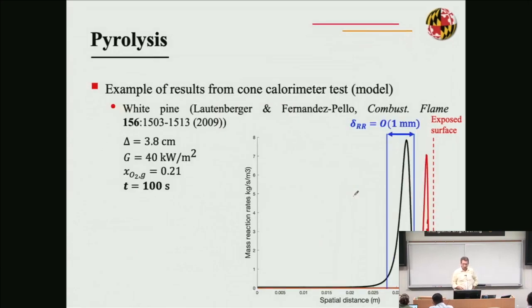All right. Here I have a description of the reaction rate. So the black line is the evaporation rate. The red lines correspond to the rate of pyrolysis, and this small peak here corresponds to the rate of char oxidation. The main reason I wanted to show these slides is, first of all, that it's important to have this insight of what's happening inside the biomass, and also to look at the length scale over which these changes are occurring. This is millimeter scale.